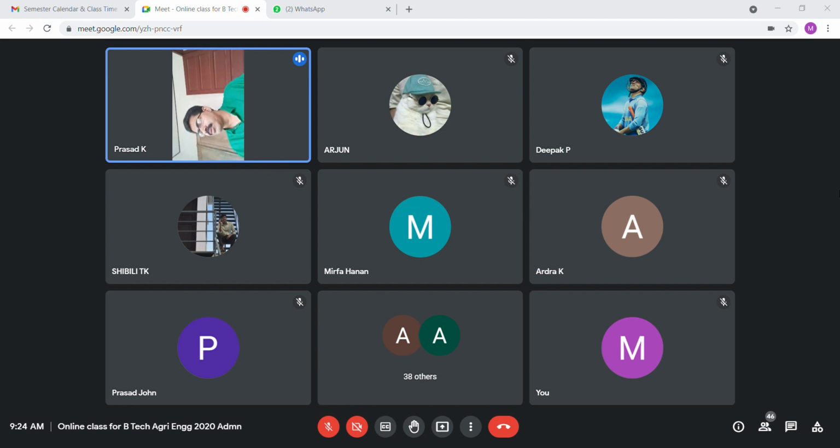In this case we have parallel, then intersecting, and the third case is non-intersecting and non-parallel. This is one way of classification, according to the position of the axis of the shaft. With respect to the position of the shaft, we have parallel. For example, this is our pulley and this is our shaft. This is one case, parallel, and then intersecting, and non-intersecting and non-parallel. This is known as the first way of classification.